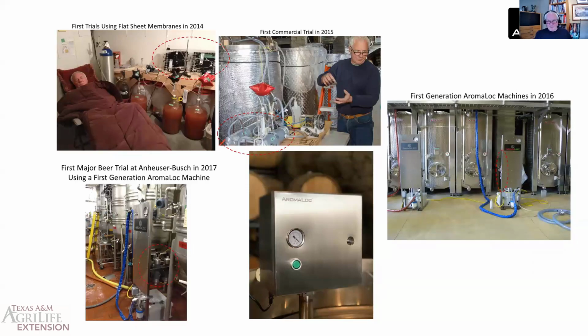of the aroma compounds in different parts of the flow circuit, those aromas are driven out of the experimental tank by CO2. So I sparged CO2 into an artificial solution containing about 13 different aroma compounds, and then we analyzed those at the local college lab. But CO2 works very well. There's no reason to think that sparging nitrogen wouldn't work just about as well. In fact, several aroma researchers use nitrogen to sparge aromas from different liquids. Now, could AromaLoc be used during sparging with nitrogen? Absolutely.